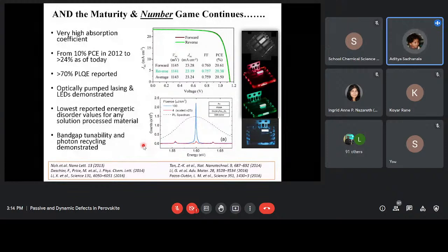The other interesting fact of all these high numbers and attractive performances is that it has very low disorder. When you measure disorder using different techniques, you end up getting values which are extremely low, and surprisingly low for such a crudely processed semiconductor. And moreover, the band gap tunability in this family is very excellent, because all you need to do is change some halogens or change some cations and your band gap is different. It's very different from what you do in MBE grown III-V heterojunctions.